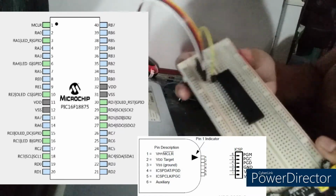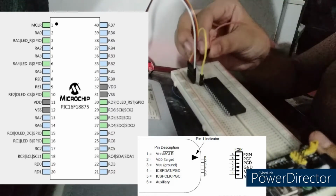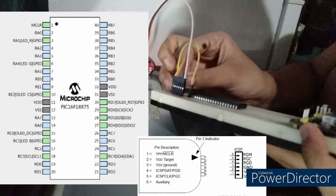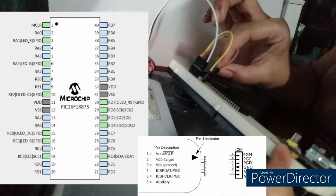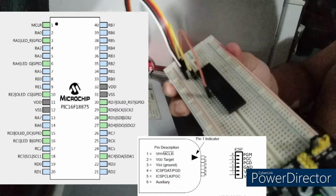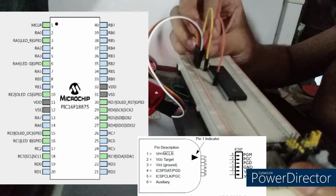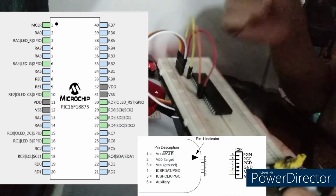So this one, okay. For our VDD here, which is pin number 2 of our PICkit 3, the orange wire, let's connect it to pin number 11 of our IC, which is the VDD as well. So let's count: 1, 2, 3, 4, 5, 6, 7, 8, 9, 10, 11. So this pin here will be the connection. Then we have our VSS on our PICkit. Let's connect it to pin number 12 of our IC here.